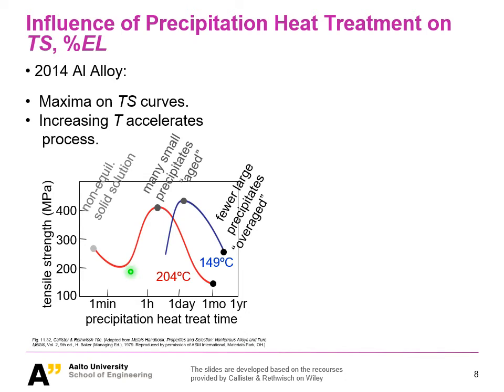But soon after, with very little time needed, you will dramatically increase your tensile strength by creating small precipitates, which is the theta phase in our case. And it is actually a little more complicated than you probably imagine, because it's not just about creating a phase, and not necessarily a hard phase. This theta is not necessarily a very hard one.